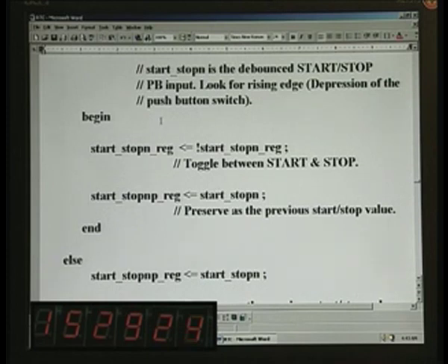And here what we should do is whenever we push the button, it has to toggle, right, because we have only one register called start stop n. The same will indicate whether it is in start mode or stop mode. The first time when your system initializes resetting, this will be cleared, and subsequently when you push the start button once, this will be made 1, and subsequent pushing will have to be inverted.